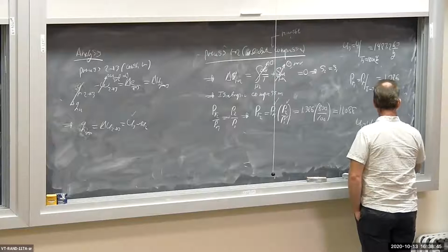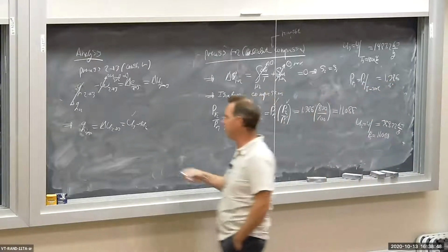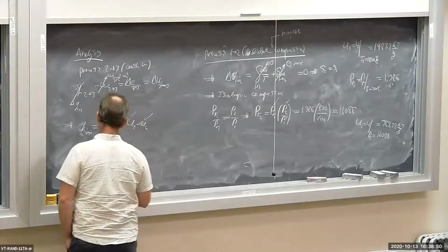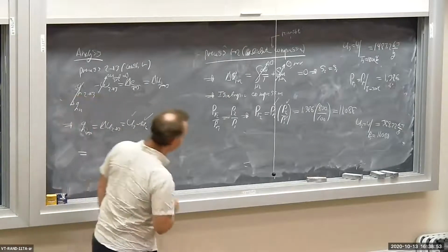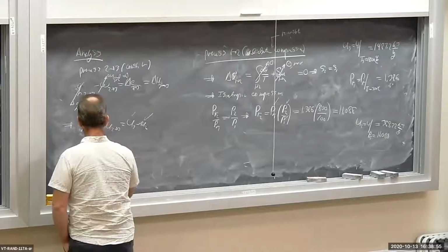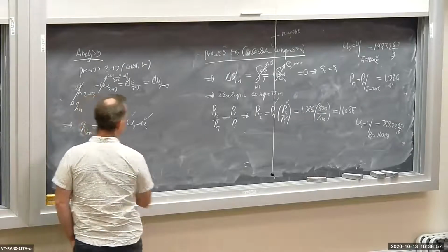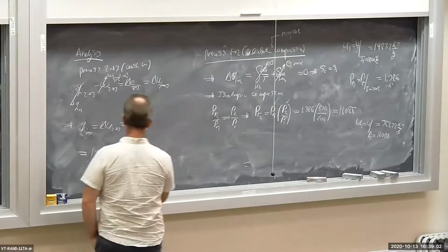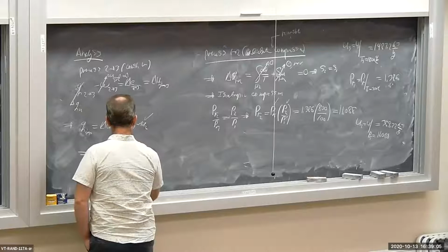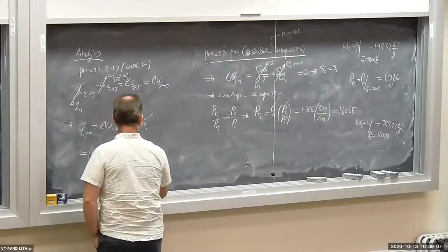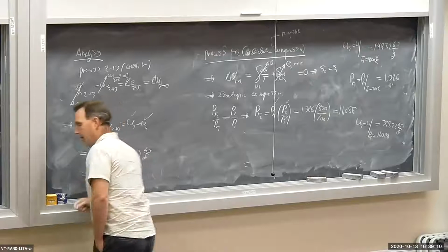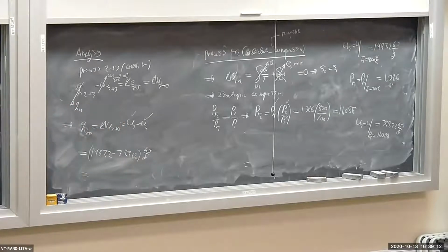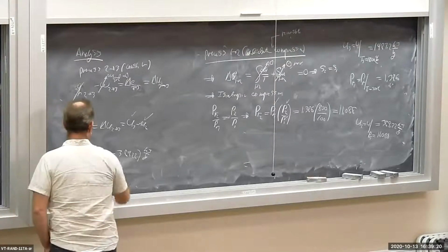389.22 kilojoules per kilogram. So now I have U3 and I have U2. Let's see here. U3 is 1114.87 minus 389.22, and that has units of kilojoules per kilogram. And I get a final heat transfer, Q in, of 1098 kilojoules per kilogram. A little bit of rounding there.